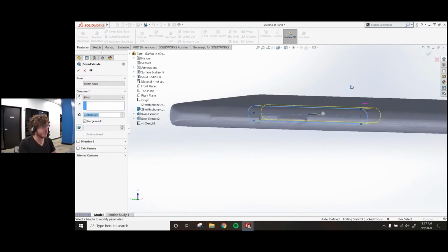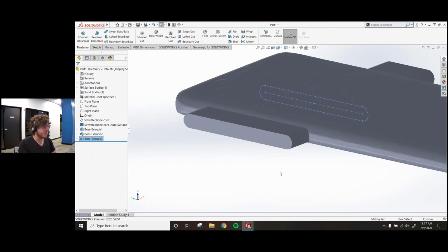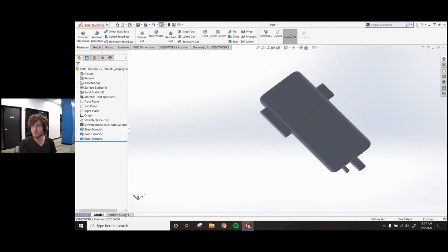And then if I extrude this out, we now have all of our buttons outlined and we have that reference body. So now we're done with our next step of this modeling process. We've done our scan, we've converted it into our mesh, brought it into our modeling software, and now we have our reference bodies. And at this point, a lot of times this is what a lot of people are looking for, this reference body, something that they can now insert into other parts.